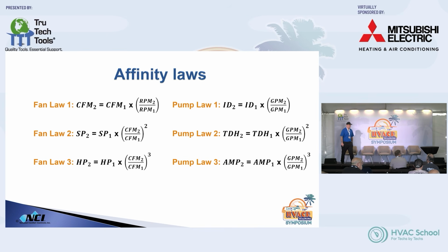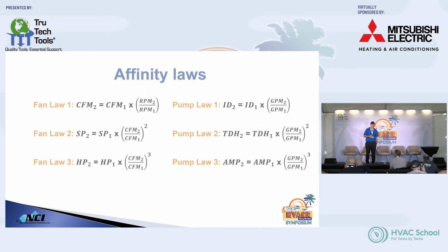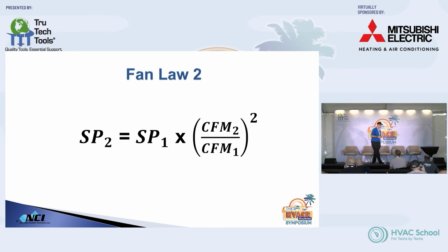So this is the math. This is what's going to put you guys to sleep. This is where the rubber meets the road, right? Fan law 1, 2, and 3, and pump law 1, 2, and 3. You could figure different things out by whichever fan law you're trying to work with, but we're going to focus on fan law 2 today. That's mostly for residential. Fan law 1 and 3 you would use for commercial, right?